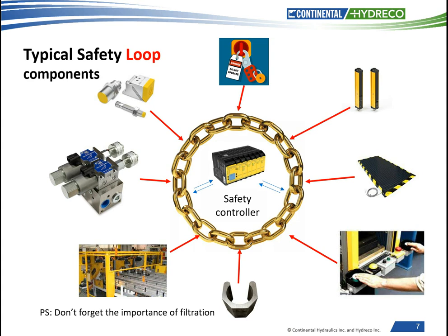If the critical function has a hydraulic valve in control, how do you know that it has indeed functioned correctly and went to the safe position? Where is the cross-checking logic? When correctly implemented into a high diagnostics coverage control circuit, these system components can meet Category 4 PL Level E or SIL 3 rating for equipment.